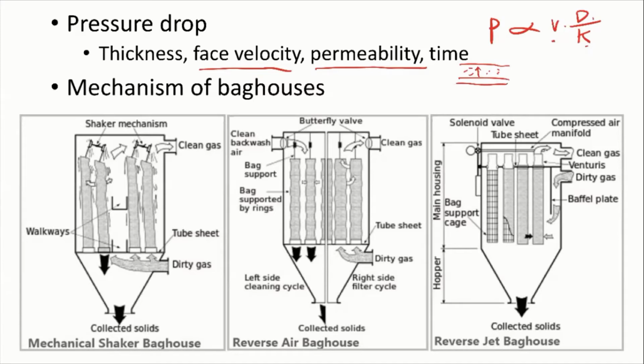Otherwise, you can see basically all the fibers penetrating from the side of the filter, right? So basically that's a leakage. What that means is that the pressure drop is already very high on the filter material, so all the particles will try to go from the side of the material to penetrate through, right?